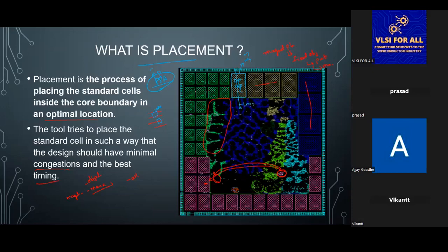Okay, if I do not add blockages, and you run it flat, you can see so many DRCs, or you can see the shorts also, because inside the macro you're using M4, and outside also you're using M4. So there will be a chance of getting shorts or DRCs. So that's why we add the blockage on the macro till M4, because internally they have used it. So it can be M1, M2, the number of layers that might have been used inside the macro. That much routing blockage we need to add over the macro. Exactly, right.